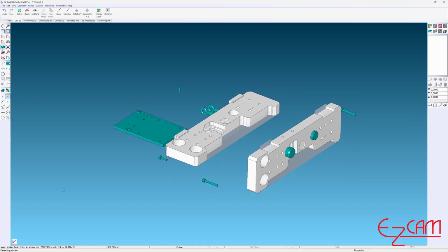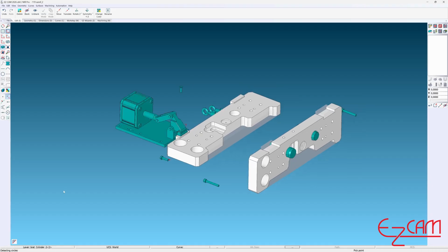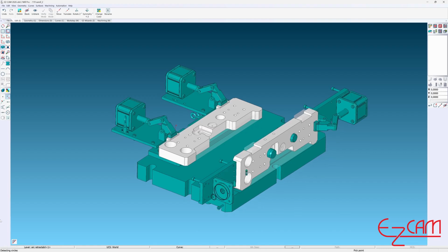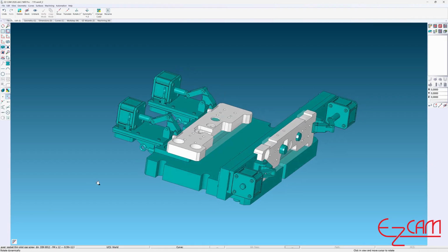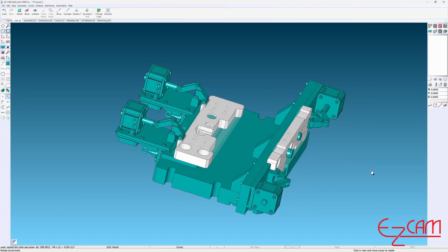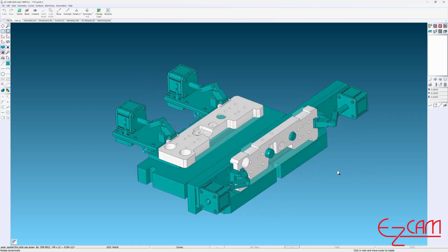At this point, we've completed all the critical steps that impact toolpath generation. Your workspace is visually ready, and all clamping and fixture elements are now included for safety. This minimizes potential errors due to oversight or distraction during CAM programming. What if a fixture causes interference during tool movements? If you forget to select them as check surfaces, EasyCam's collision detection will notify you during simulation.